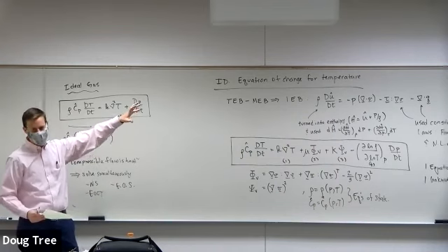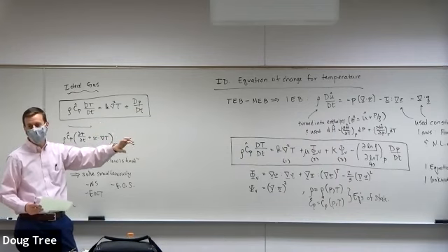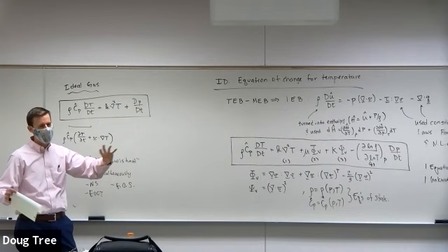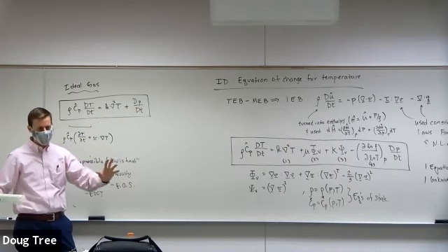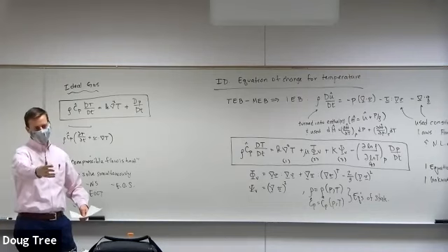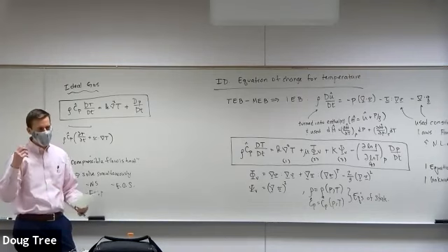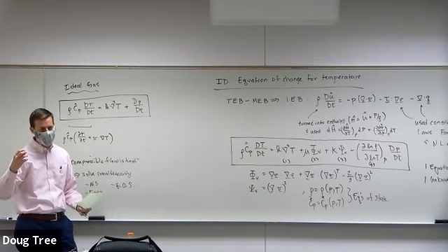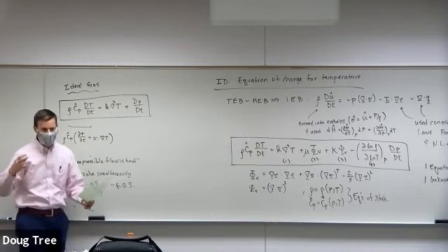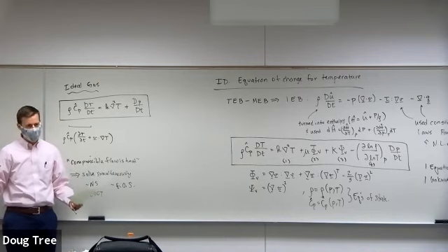We're talking about how to solve fluid flow equations. As soon as you introduce compressibility, stuff gets a lot harder. And so maybe that's also the lesson: if you're using OpenFOAM to simulate incompressible flow, and you start to think that compressibility is important, you need to take a step back and consider the broader problem at that point, because it's going to get messy really quickly.